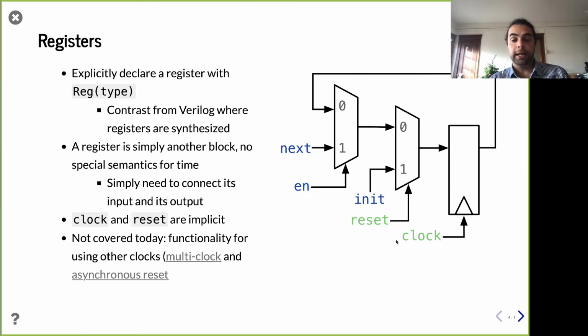So as a reminder of the semantics of those signals, I've made this little diagram here, which shows behaviorally what is going on. We have a register we're trying to set to the value next, potentially. So what's the potential part? Well, you can imagine under the hood, this isn't quite how it's done, but you can imagine there's a mux. If the write enable is on, then yes, the next could become the next value register.